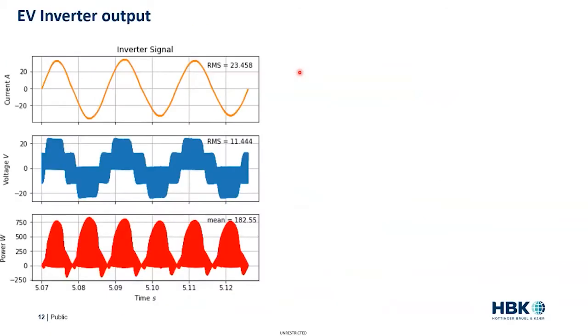So if we look at this, as the data's coming off of our eDrive system, we see here, this is the current, and it's nice and sinusoidal. Okay, but the voltage is anything but. This is done by effectively a pulse width modulated signal, so a digital signal, so that when it's smoothed, it gets the current sinusoidal, but the voltage itself is non-sinusoidal. It's very lumpy.